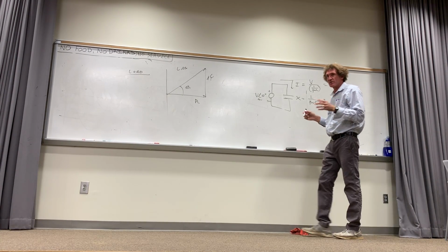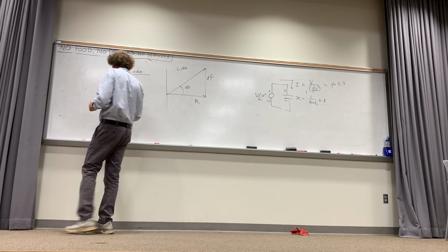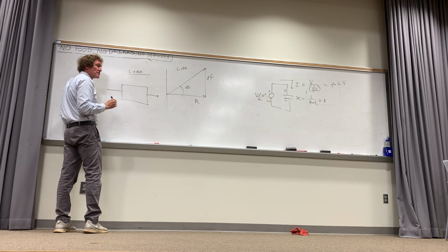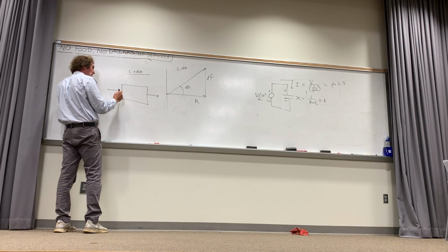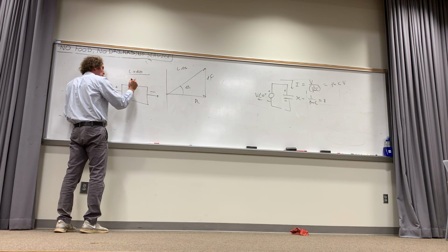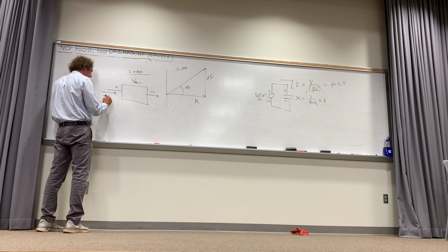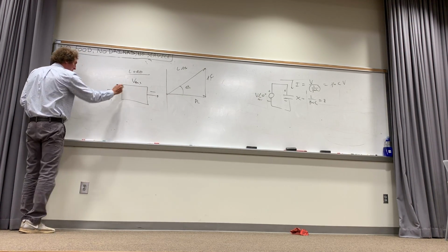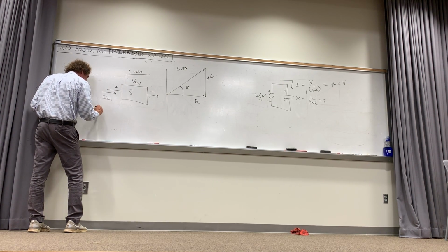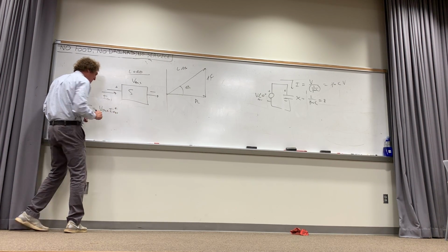Now complex power, this is important. This is the voltage, that's the direction of current. When I talk about complex power, and I have anything at all, doesn't matter if it's a generator or if it's something supplying power, if there's a plus to minus voltage V across here, and put RMS, and there's a current entering the positive terminal, then the complex power associated with this, the S associated with it, is equal to V RMS times I RMS conjugated.